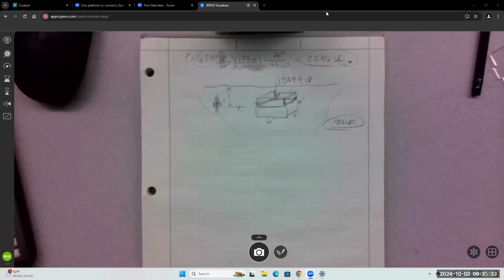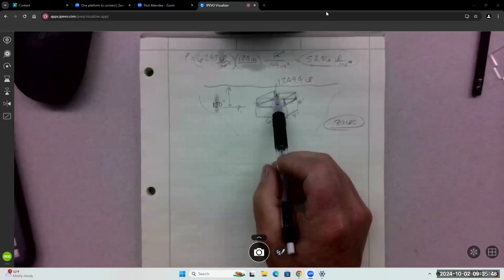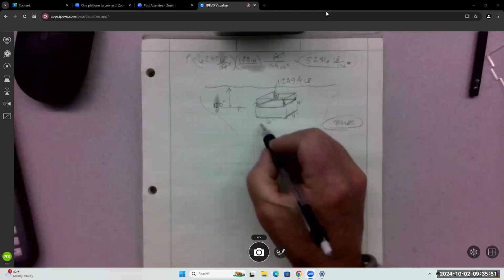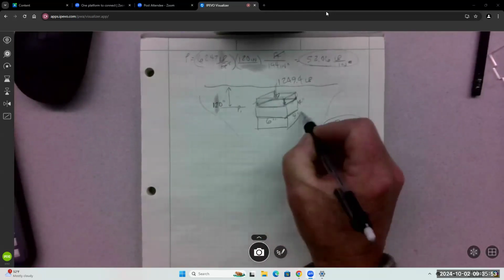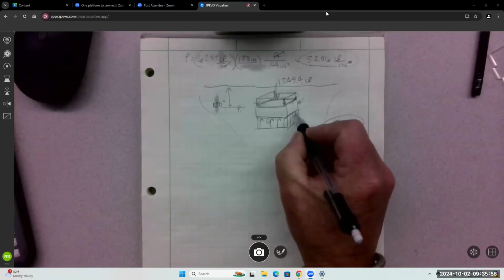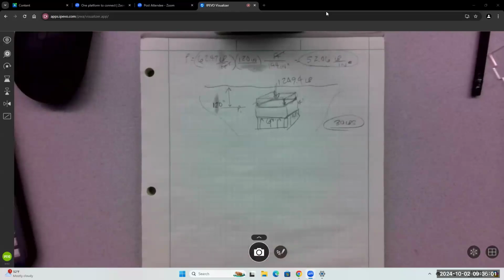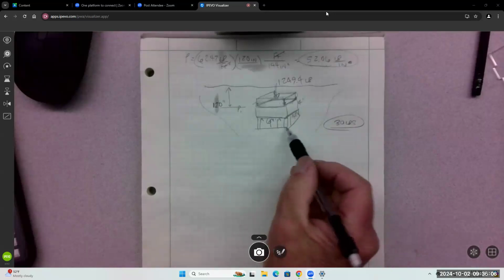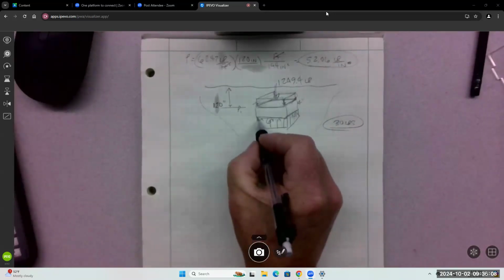So for the two surfaces that are also 6 times 6 by 4. Can we use that number for the lower pressure? So you're heading in the right direction. This is the water pressure acting down. There's the same shape down here. Is this what you're talking about? Yeah, on the bottom, this same thing is happening, right? Because it happens on every surface. So down here, it's the same shape, but what's different?